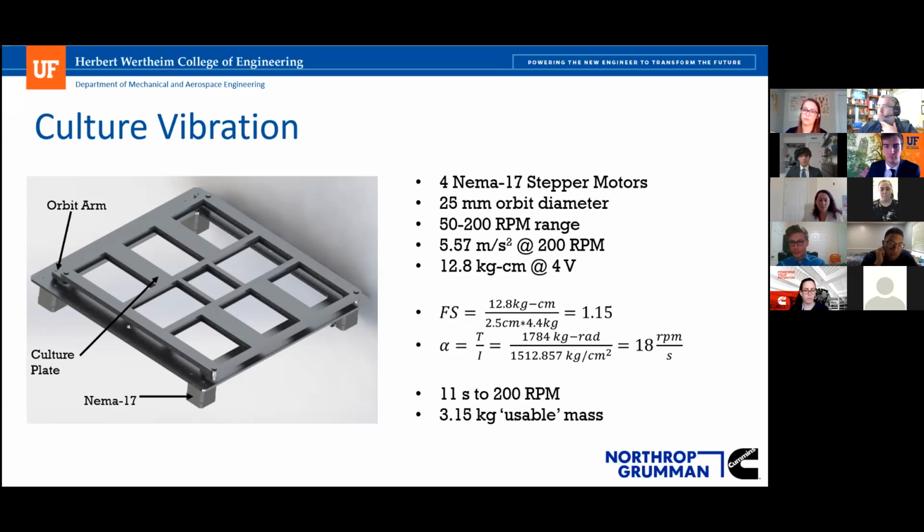So we're going with an orbital shaker at this point. There are some possibilities to just reverse the polarity of the stepper motors at 180 degrees and make it a pseudo linear shaker, but we've performed some analysis on the orbital only. Based on discussing with the customer, the shaking patterns are there to not only agitate the fluid a little bit, but also reduce the risk of that outer growth layer happening on the samples and impairing the OD and FI measurements. We felt that an orbital shaker was more than sufficient given those two constraints. The reason why that's cut out in the bottom is to allow for measurement of OD and FI, so that's kind of why it looks like it does.